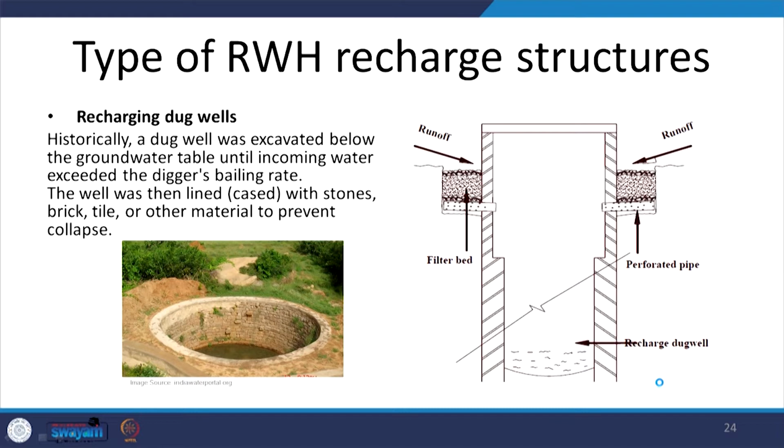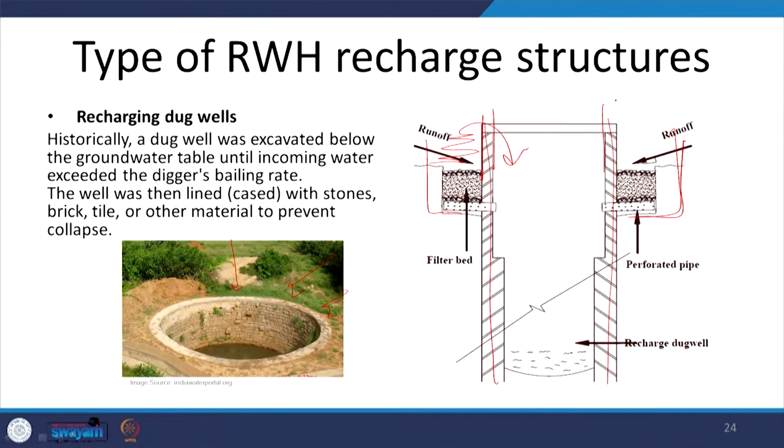The next is the concept of dug wells. Now, here we actually have a well in the center like a normal traditional well as we understand. Around this well we will have a filter bed. So, all the water which runs off to this well, if it overfills it, may directly enter into it, but that is not a good idea, because a lot of pollutants and suspended particles may then enter the well. So, that is why the sides of the well are raised, so that direct water does not come into the well, and there is a filtration media, a perforated drain, where the water when it comes filters through it, and then it goes on to recharge the same well, which may then later be used to draw the water up.